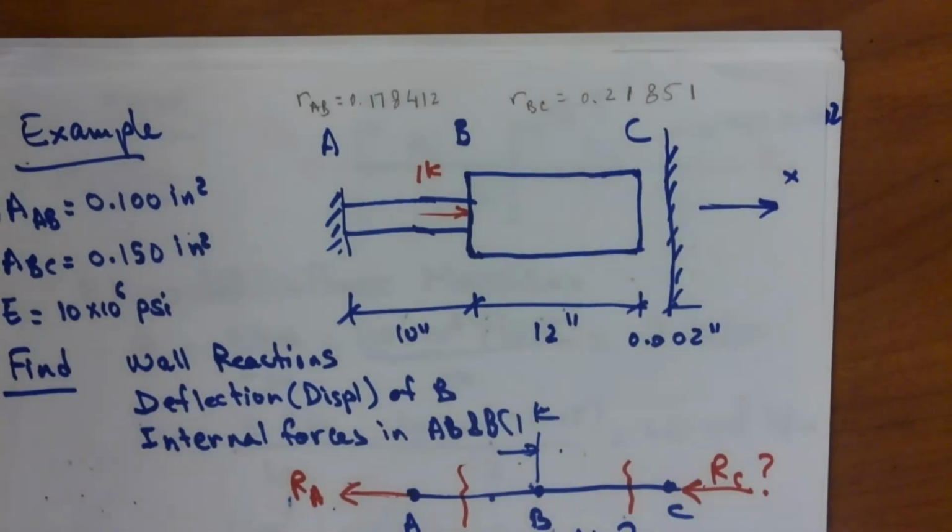So I'm starting here with a fresh new project in ANSYS Workbench. Before I jump into that, I want to make sure I have the correct units. So I will go to units, and we are clearly using US engineering, pound, inches, seconds, etc. So these are the units, and we want to make sure that we display the values in the project units.